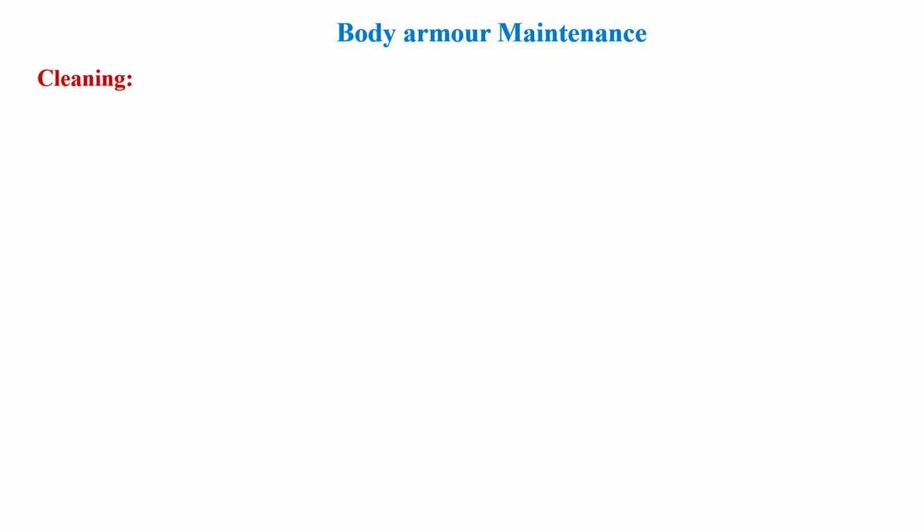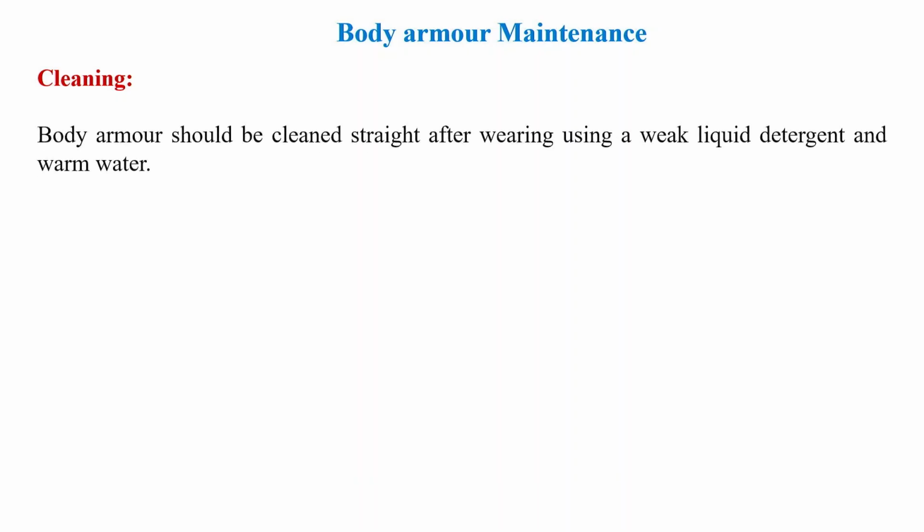Body armors should be maintained properly to keep their performance intact. So, cleaning should be done as per the standard. The body armor should be cleaned straight after wearing using a weak liquid detergent and warm water. We should maintain this, otherwise there will be a bacterial impact which may damage the fiber and the performance may deteriorate.